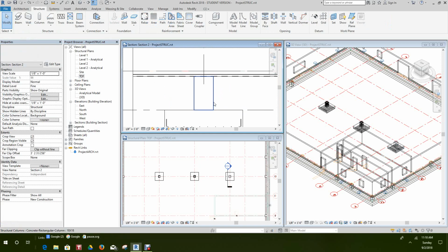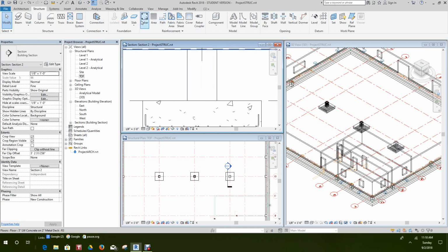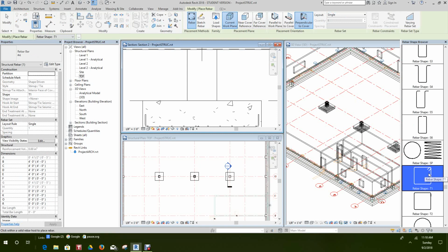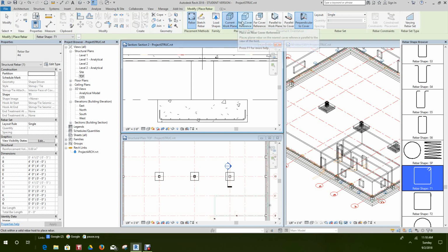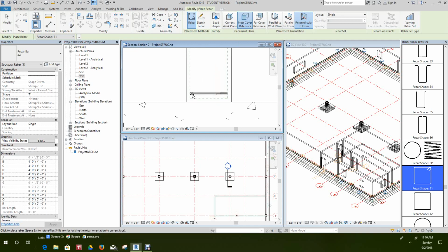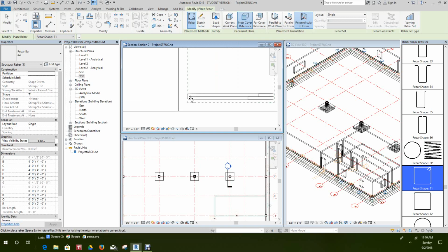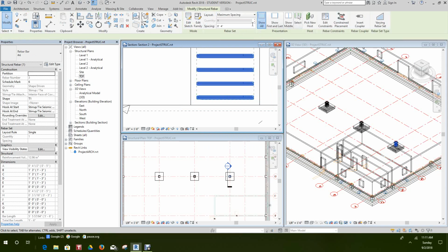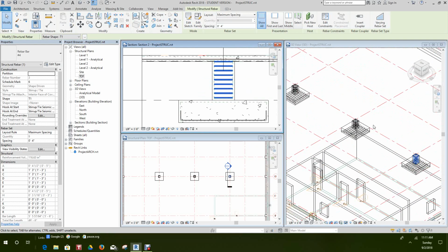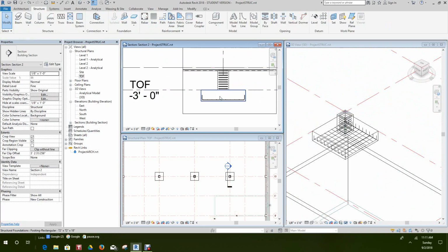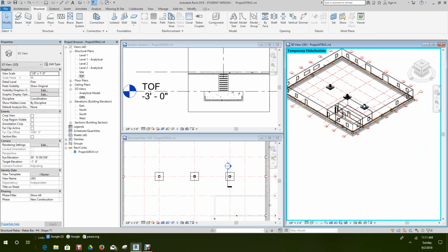Now let's go and do our stirrups. Okay, so let's go Rebar. Our stirrup, and we'll go near cover, perpendicular. Place it right at the cover line. It gets a little tricky here, but there. And we didn't set our settings first, so let's go here and go maximum spacing. Where are we going with these? At 8s? Let's leave these at 4 since it's a column. But anyway, that's how you do reinforcing in our footings and columns.